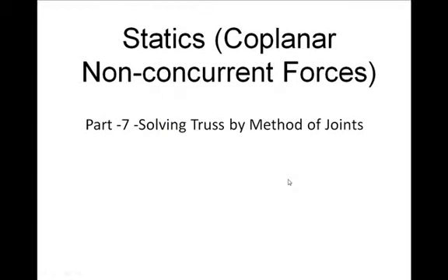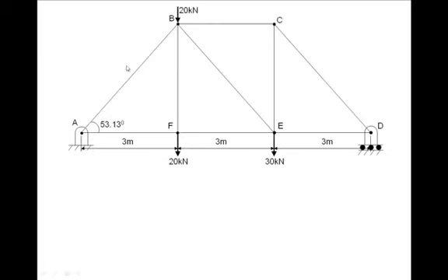This is a video on statics of coplanar non-concurrent forces. This is the 7th video in the series, and here we are solving a truss by what is called the method of joints. Now this figure is a truss.